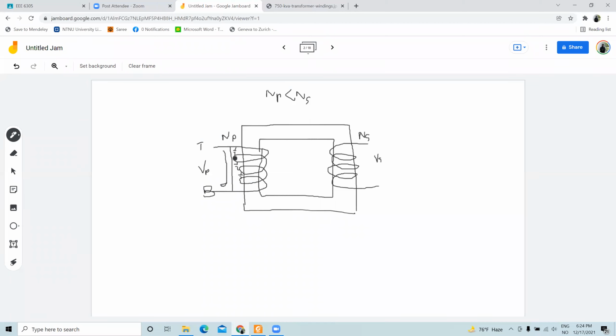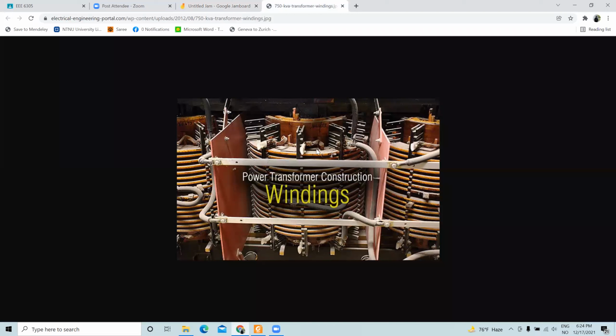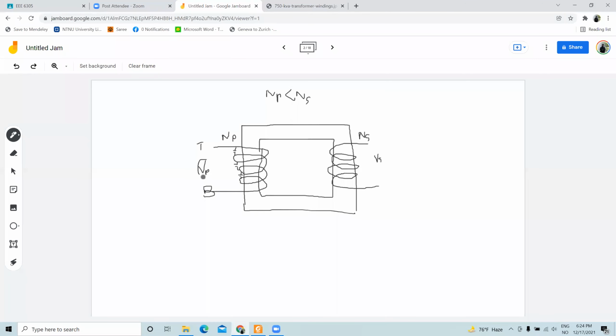Yes, sir. So you do not want your current to flow through the shorted path. Instead, you want your current to flow through these windings, and that is why you have to have certain insulation between the windings. That is what you can see from this paper insulation. On top of these windings, you basically have paper wrapped. Now from top to bottom, you basically give your voltage VP.